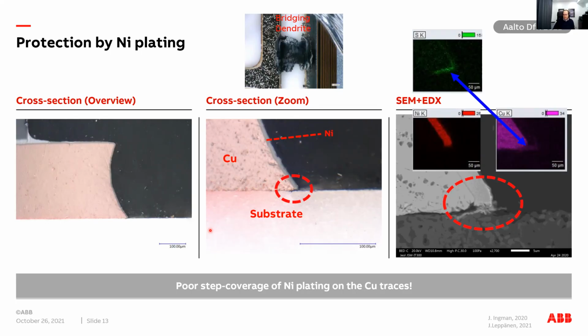Yes, exactly. On the other hand, I think this 60% is just that in theory it is possible to have electrolysis there. I'm not saying that at this point we would do any tests. Definitely I would always do this kind of testing at 85%. It's really far beyond this 60%. And if you can get a component that would be immune to all these phenomena in these tests, you would have really good reliability with respect to environmental impurities.